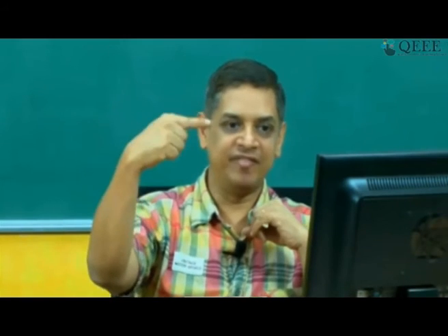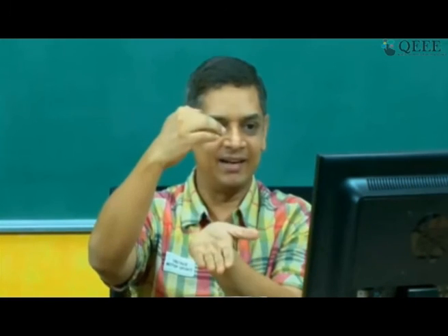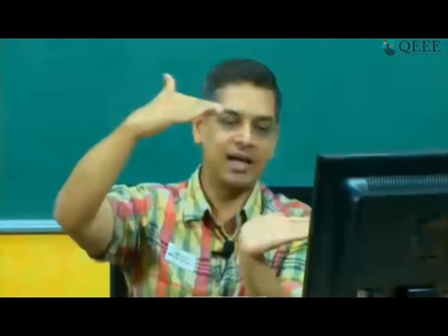That is the force in the flange. That force has to be part of the bending if it is to be connected. It is actually coming all the way from the top down. Similarly, there's a tension in the bottom flange. They neutralize each other at the neutral axis level. So that is the force that's called longitudinal shear. It will depend on the bending moment that we are applying on the section.